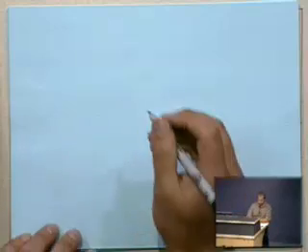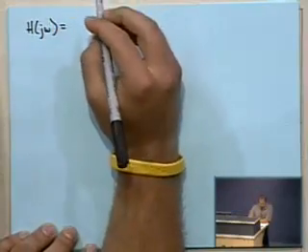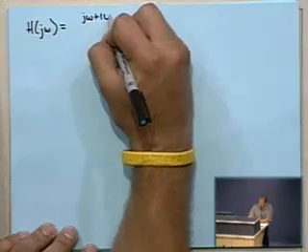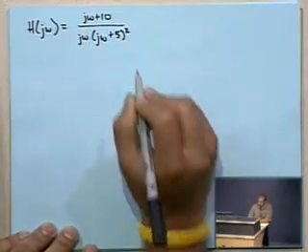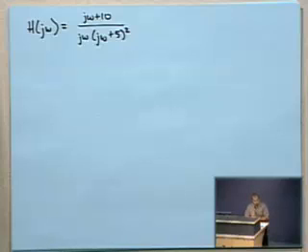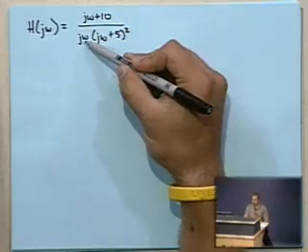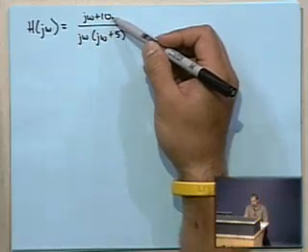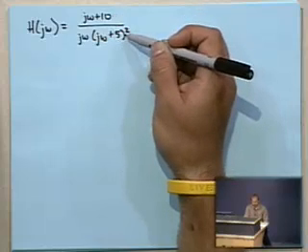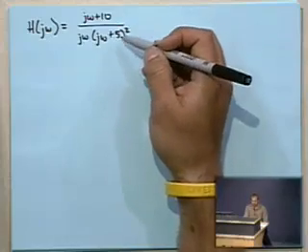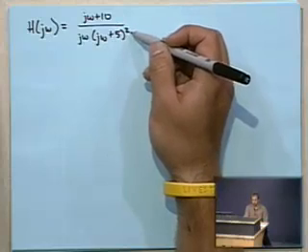So one more quick example and then let's be done with Bode plots. Here's our last transfer function, which is j omega plus 10 over j omega times j omega plus 5 squared. What we have here is a pole at the origin, a zero at 10 radians per second, and another pole at 5 radians per second. I've heard people refer to this as a double pole because of the squared term here.